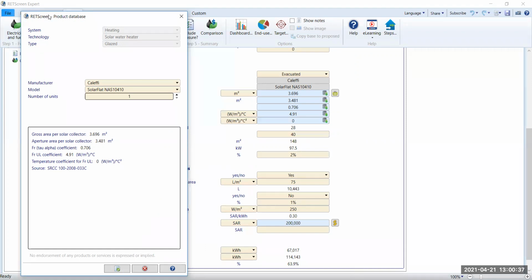But in a swimming pool, you don't need high temperature. So you would probably go for buying what we can say is a cheap collector that's going to heat the water only up to maybe 30 to 32 degrees centigrade. So you are making a cut in the cost of the solar collector, knowing the efficiency is not high, but it's okay because the temperature needed is not high. Okay. Thank you. Okay. Fine.